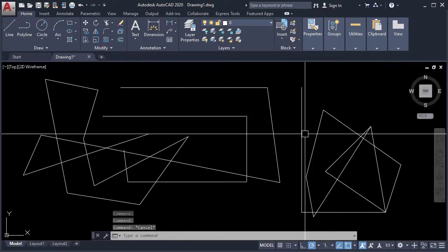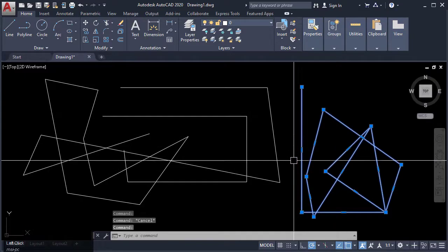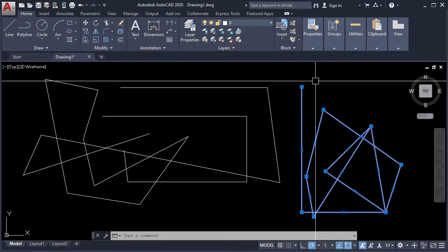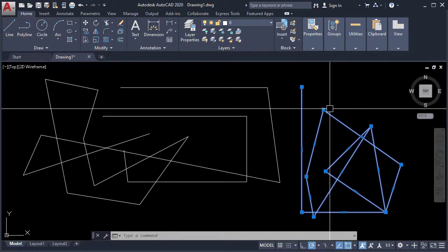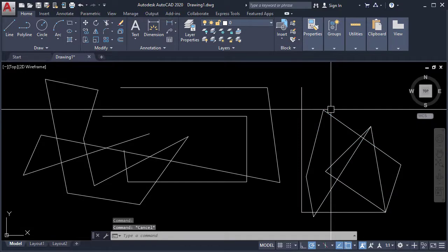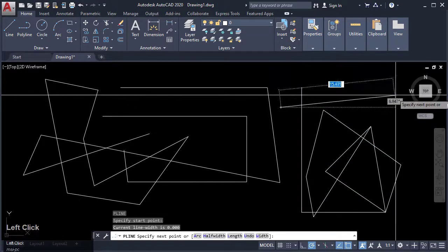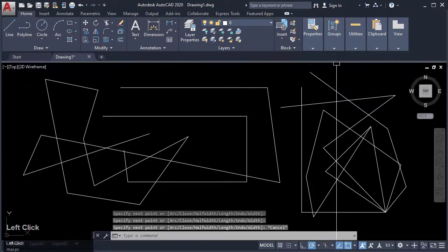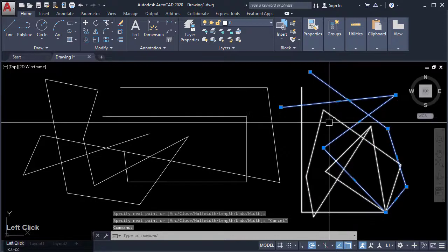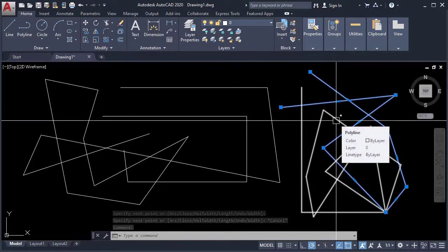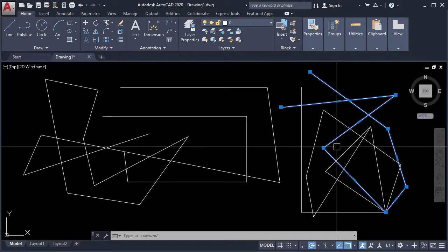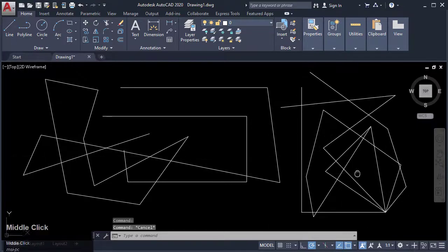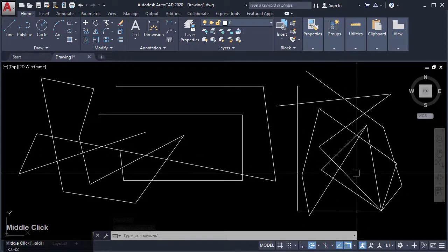But if I choose polyline, one thing that you will notice is that the polyline acts as a single entity. All of the lines are interconnected. This one is of course different if I place another polyline, Escape key. Escape. What you will notice is that each polyline is set apart as a unique set depending on the termination of your polyline. So that's the difference between your line and your polyline.